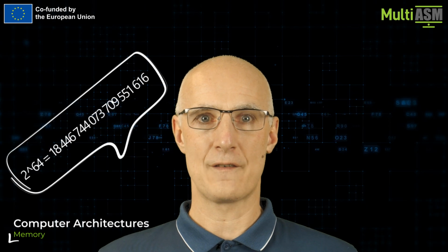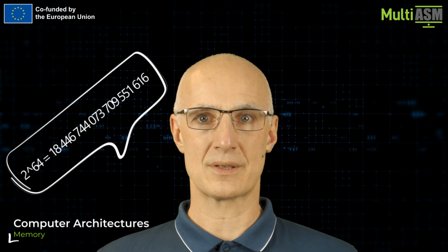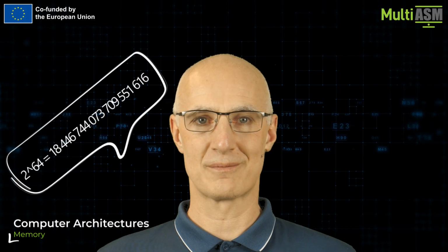So here the number of bits of the instruction pointer is significantly longer. Modern 64-bit processors have 64 bits of an instruction pointer. It means that it can access more than 18.5 thousand petabytes of memory. It's a really huge value. For comparison, the Frontier, one of the most powerful supercomputers, has 10 petabytes of operational memory. The actual number of bits used to address memory in personal computers is limited to 48, which gives the theoretical address space of 256 terabytes.